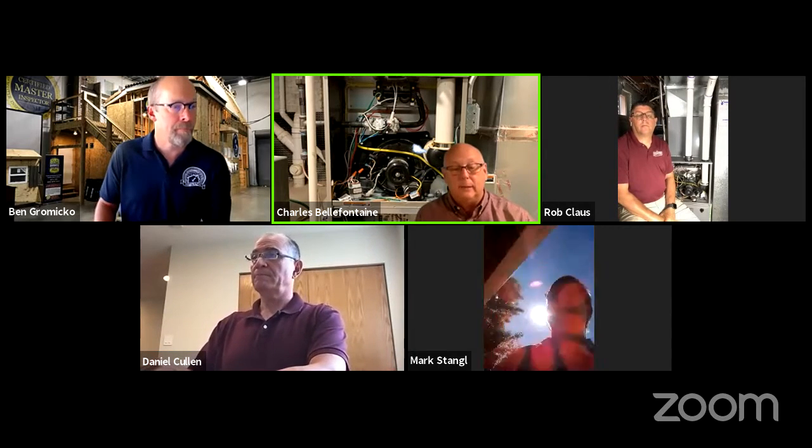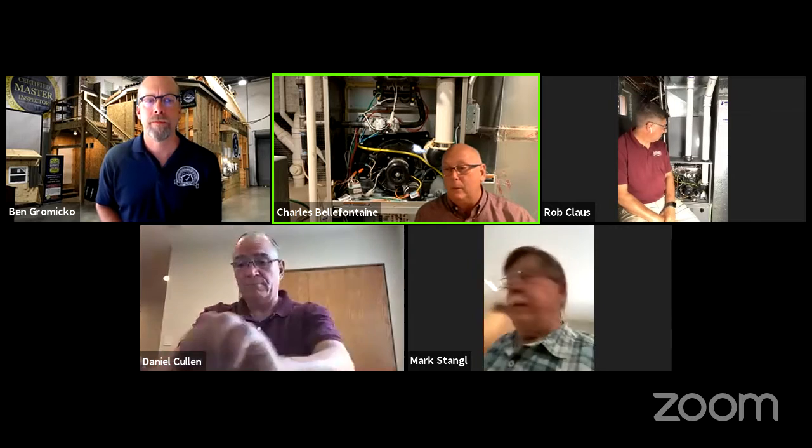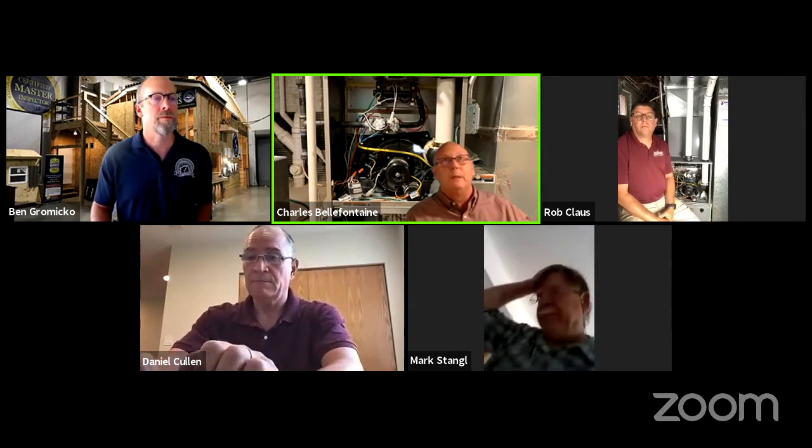I like to add on, before I check for time on this, there's kind of 3 different safety things that are built into a furnace. And by no means does it mean that if you have one bad thing, you can ignore the others. All right. But let's say the first thing is going to be our gas air mixture. If that's in good shape, then we're going to be producing hardly any carbon monoxide whatsoever. If it's a bad gas air mixture and we get high levels of carbon monoxide, then obviously if we have a hole or crack, that can come into the breathing air as well.